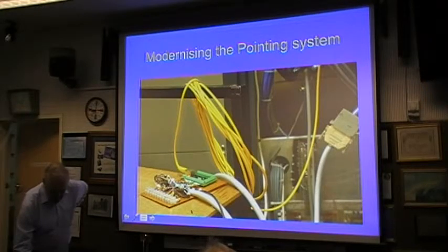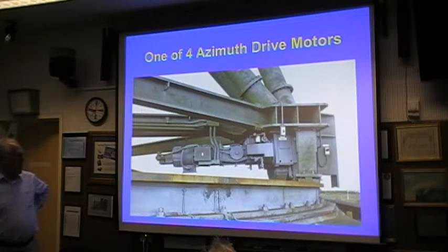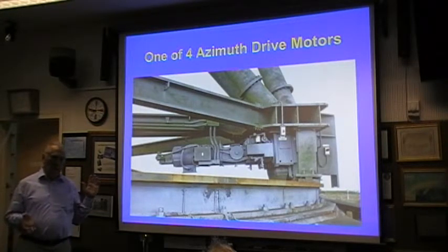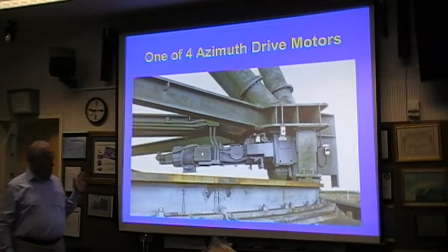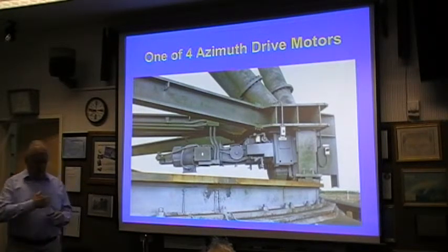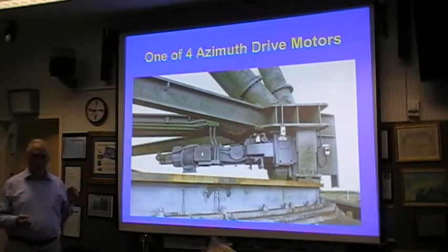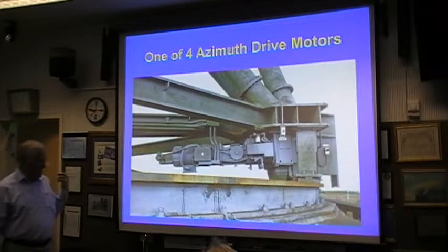The motors that are driving the azimuth, here is one of them. They're fairly substantial, 4 of those. At one point we were trying to operate EME. We were trying to work a VK station. Actually, I'm ashamed to say I've forgotten the guy's call sign. Somebody will probably tell me. We had a sched with him, but we wanted to check Taurus or something, which meant trundling the dish round through 180 degrees. At that point, trips went on 2 of the motors, and we couldn't get them to go back. So we were moving at sort of half speed. It was all pretty dreadful.